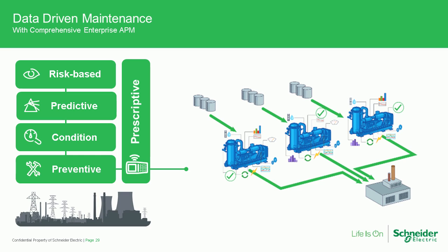Data-driven maintenance, talked about this. These are the levels that we see of maturity around the approach to maintenance or preventative maintenance. Every week I do something to my pump. Then condition monitoring, so looking for things like, hey, there's a rising current in the windings. I'm taking more current into my motor than I usually do, so that means that there's something wrong and you need to go look at it.